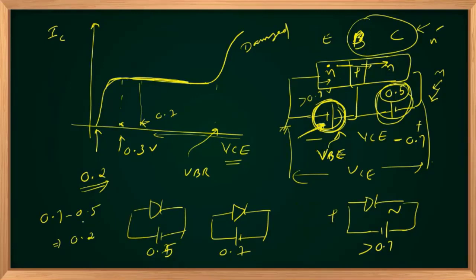That voltage, the voltage between collector and emitter, we will call VCE saturation. Why is it called saturation? Normally this is forward, this is reverse biased. So we decreased this source voltage, the DC source value. We made it negative, negative 0.5. At that time it completely blocks the currents due to the emitted electrons from the emitter region, and none of the electrons are collected by the collector region, right?